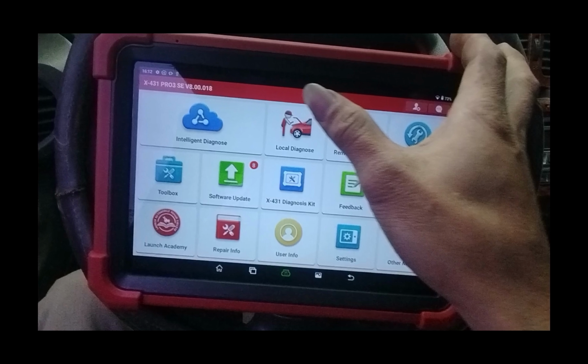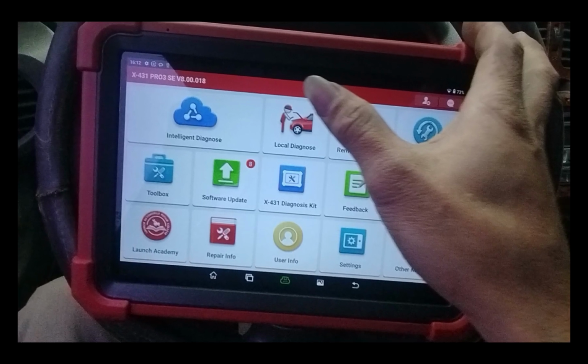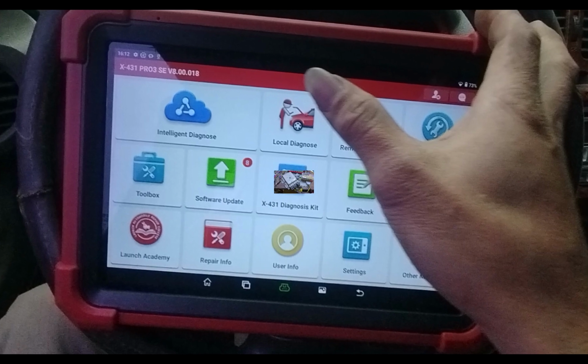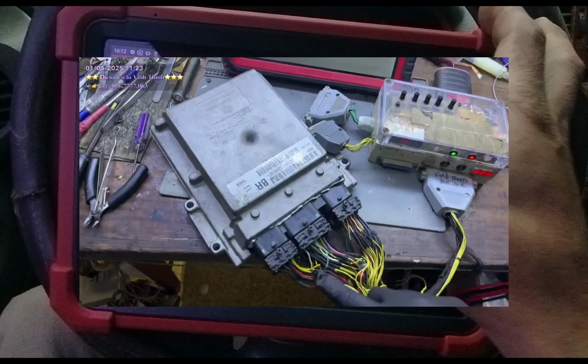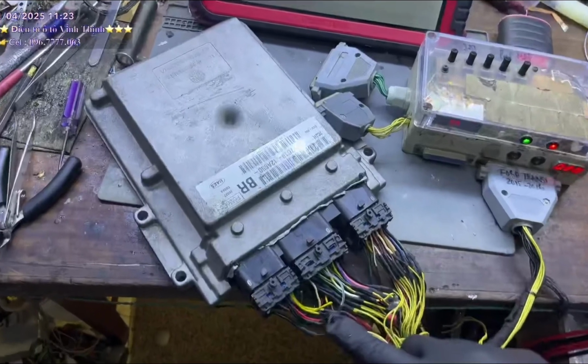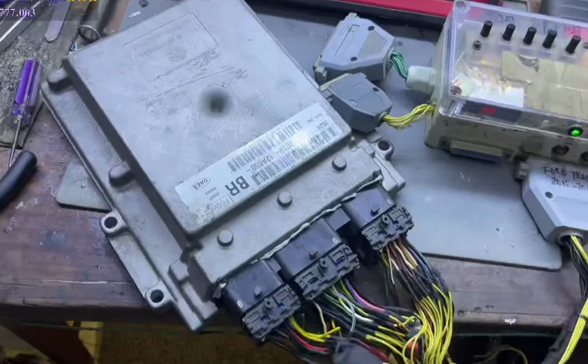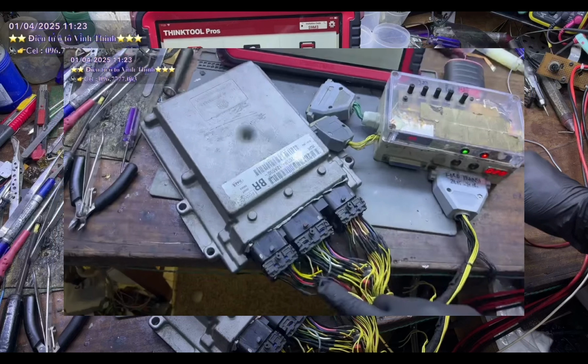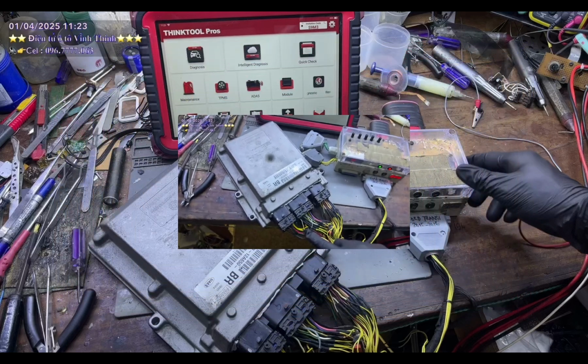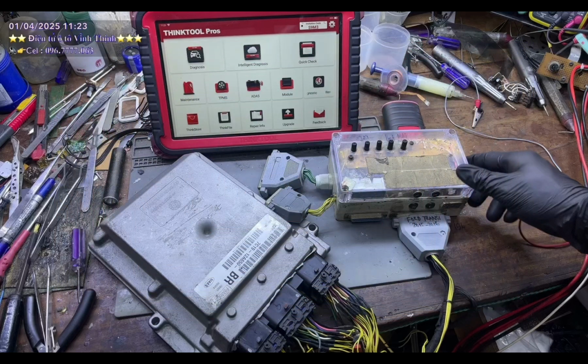4. Application in ECU diagnostics and engine electrical systems. Understanding how the engine operates helps technicians diagnose engine faults using sensor data from the ECU. Inspect and repair key components such as camshaft sensors, crankshaft sensors, fuel injectors, spark plugs, and ignition coils. Understand how the ECU controls fuel injection, ignition timing, and variable valve timing, VVT, making it easier to identify faults accurately.